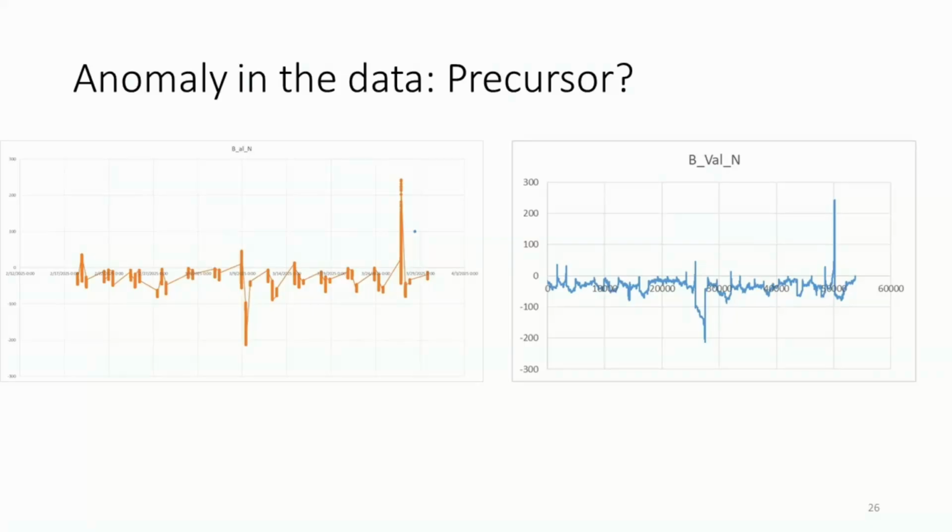And if you want to just plot the values without attention to the time, the right side panel will appear, and the earthquake can be seen in the left panel by a blue dot. So we can see there are two anomalies. We believe, because of our experience in previous years, that the geomagnetic precursory data shows that the anomaly is always in reducing the geomagnetic field values, not in increased values. So we believe that this anomaly can be considered as the earthquake precursor.